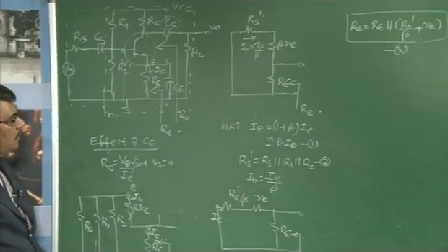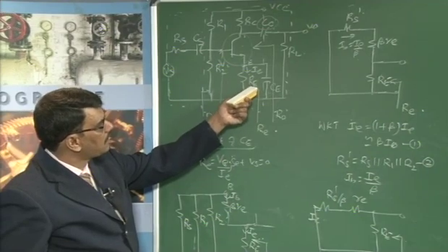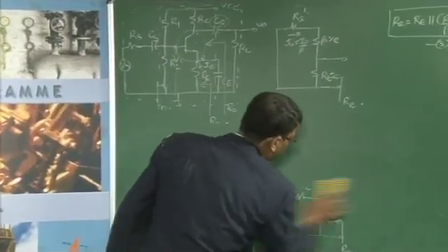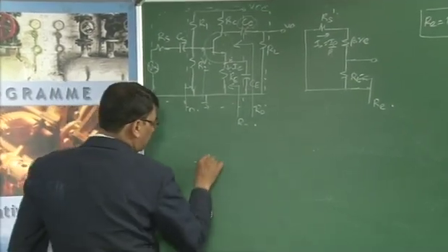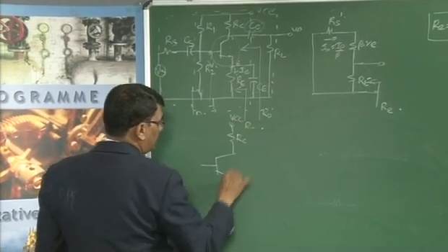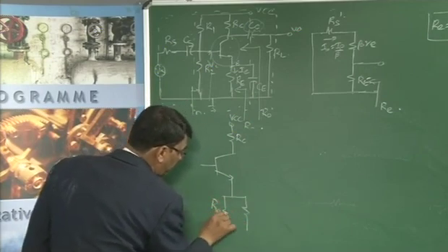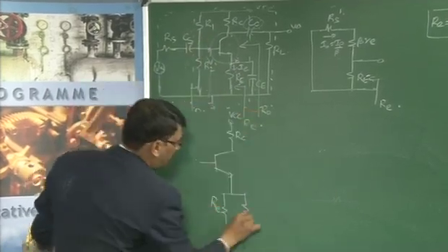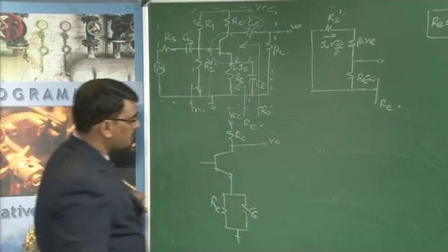Okay. You found that when you are looking into the network, the transistor network resistance value is equal to R_E. Then this circuit, as a transistor amplifier circuit, looks like this: this is a transistor, there is some resistance R_C with equivalent V_CC, then at the emitter there is a parallel combination of R_E and C_E, and this is grounded. Output is to be taken across this point.